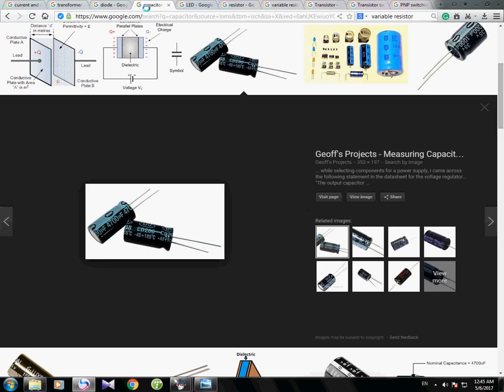In the case of an electrolytic capacitor, you have to remember the pin configuration, that is one terminal is positive and another terminal is negative. So how will we find it? If we observe the body of this capacitor, here is the negative marking. The closer terminal is the negative terminal and the opposite terminal is positive. Another way you can find out the pin of a capacitor: the big one is positive and the short one is negative.